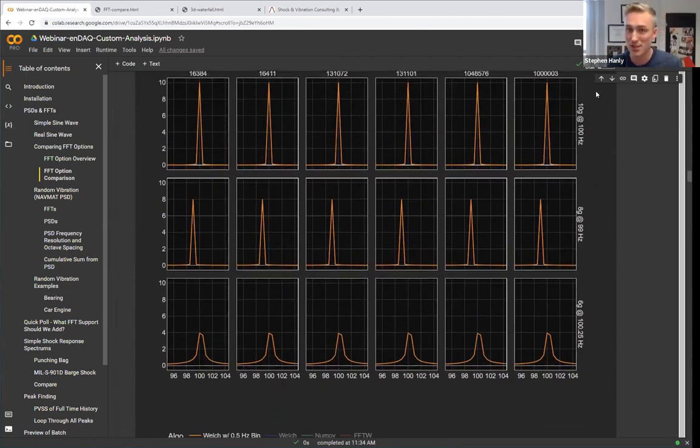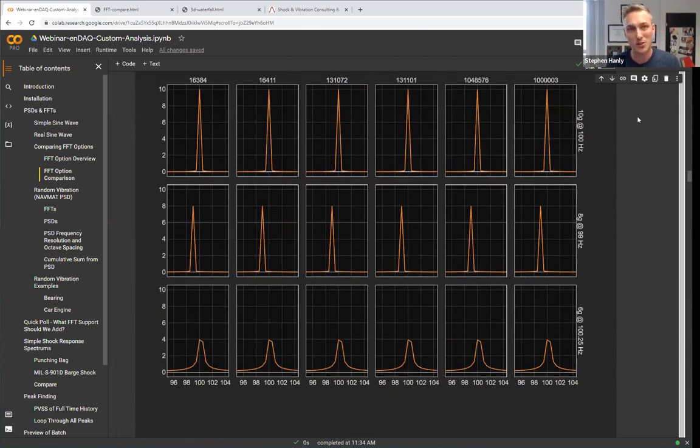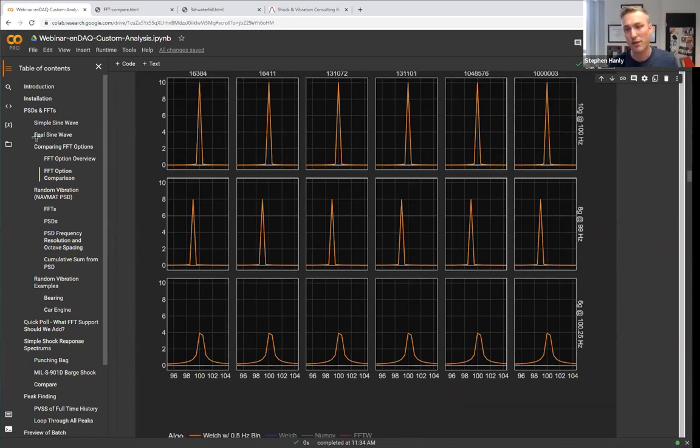Now, when we use Welch's method, we get the benefit of averaging a series of FFTs together, and now you see pretty consistent results. Very consistent results regardless of the length of time. I think that's pretty impressive, and this is a nice way to compute an FFT. You see here it's the same thing for everyone, a peak exactly at 10 Gs, exactly at 9 Gs, or at 8 Gs.